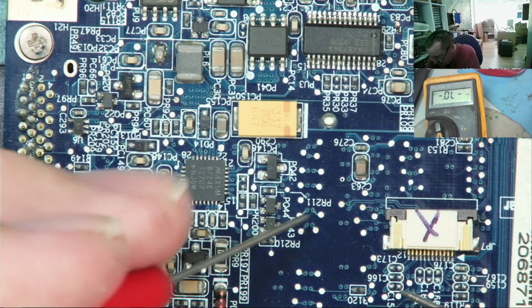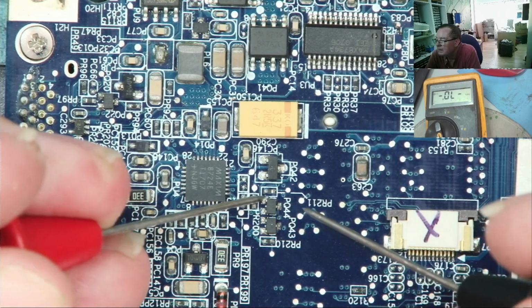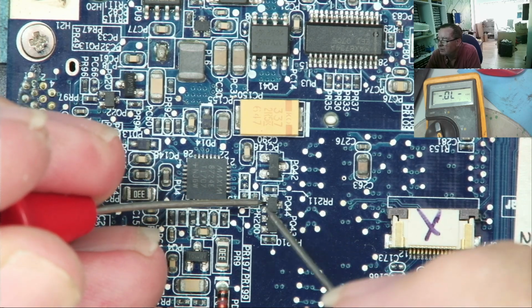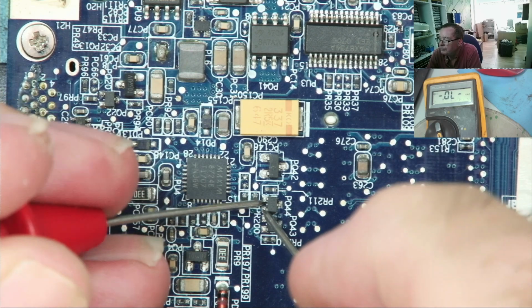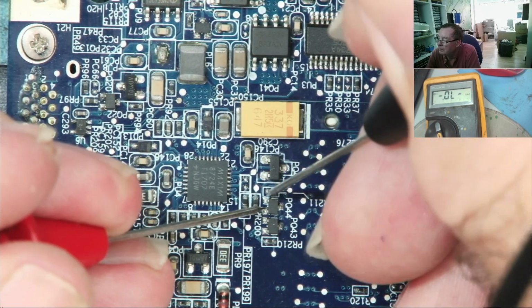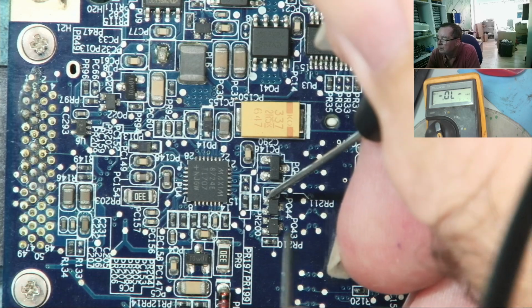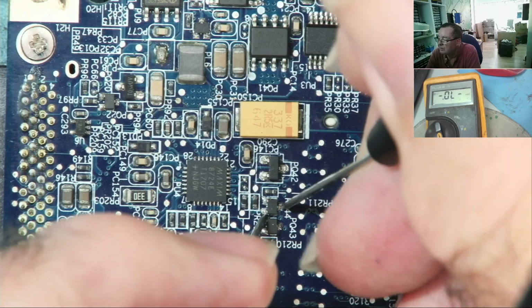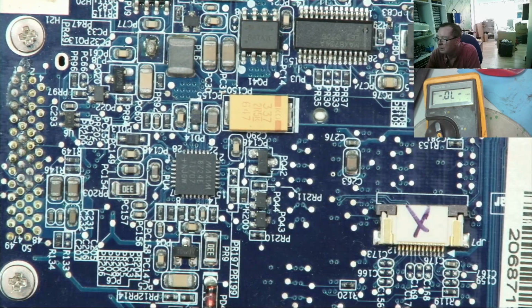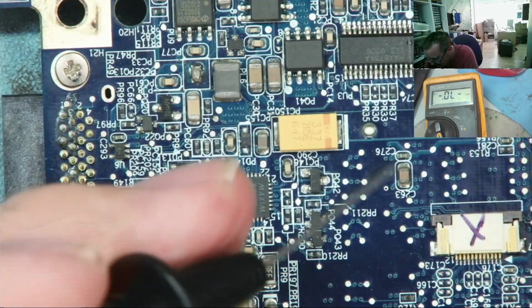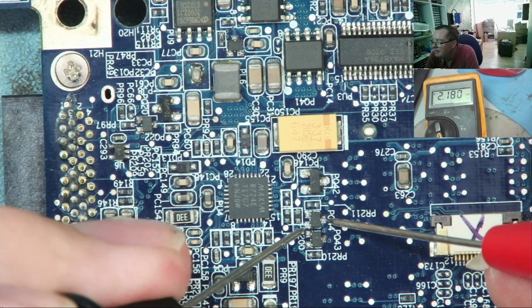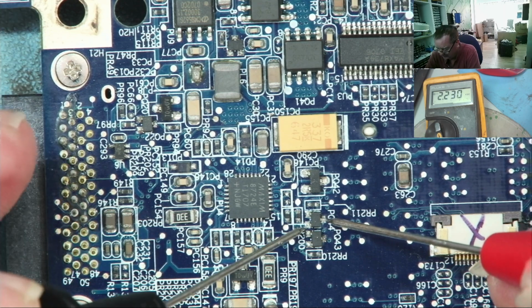What's this thing read? Again, base or gate. What have we got? Nothing. Go the other way around. Nothing. Nothing. Again, does it read a parasitic diode? Yes. Other way should read open, you would think. Haven't lost it. It's there. Okay. Reads open. So that reads like another MOSFET.